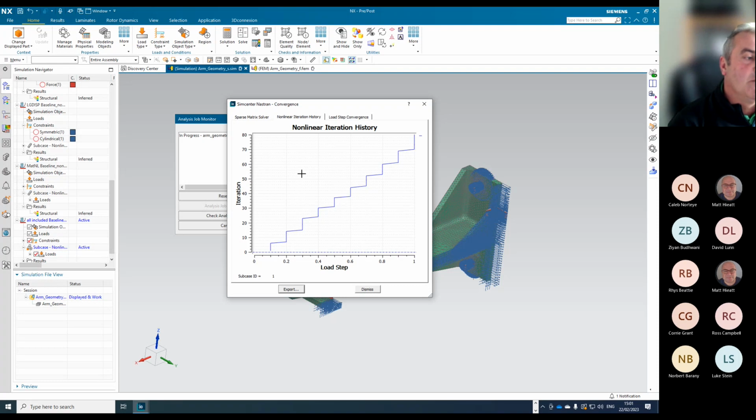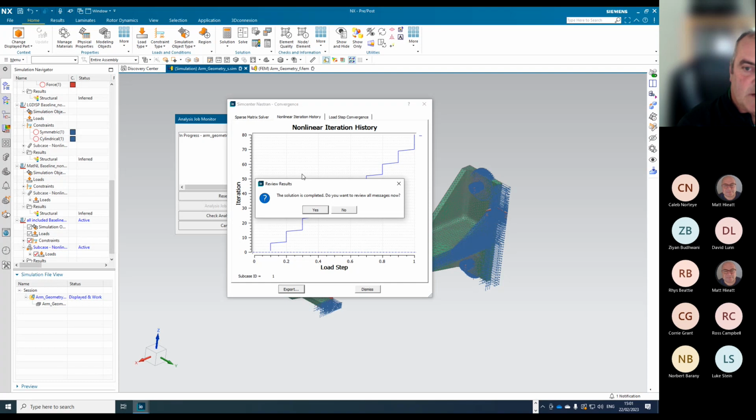Where we could start and do a bit more with the 401, 402, you could do bolt tightening sequences, where you could decide which order you want to tighten the bolts, then go ahead and do a static analysis. Then you might want to do a dynamic analysis of that statically loaded structure. So you can do all of that with 401, 402. So you can start and look at manufacturing processes as well.